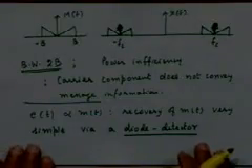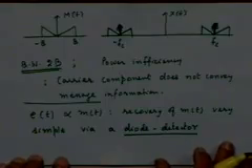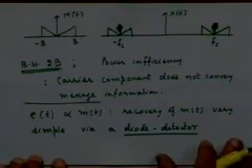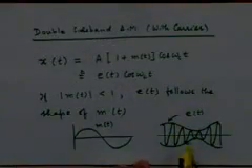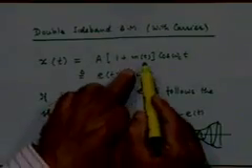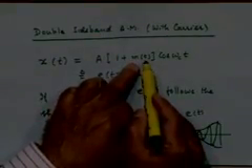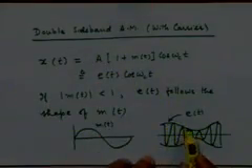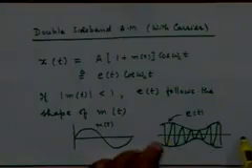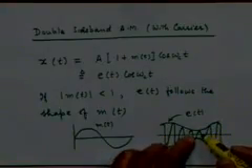But before I go into the diode detector, which we will give you in a few minutes, it's a very simple device. Let me also define some attributes of the waveform that we have just talked about. The waveform I am referring to is this modulated waveform. Depending on the relative value of modulus of m(t) with respect to 1, the envelope can be fairly above the time axis, or it can even touch the time axis.